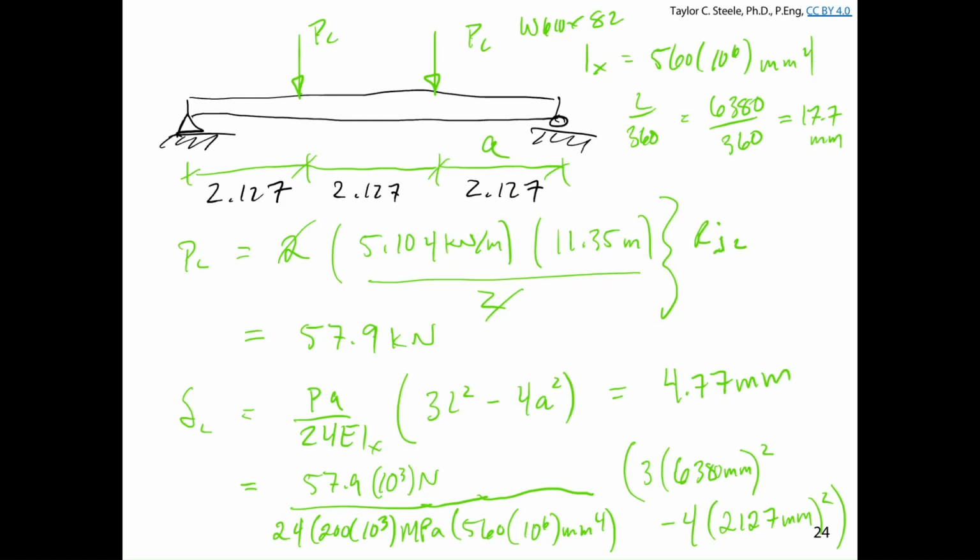And so even if we had the strictest limit on deflection for our girder, we're well within that limit, right? We're not including the permanent dead loads there. If we had non-permanent dead loads, we could include a little bit more deflection from the non-permanent dead loads, but we'd still be at a deflection that's well within the upper limit on deflection for the girders.